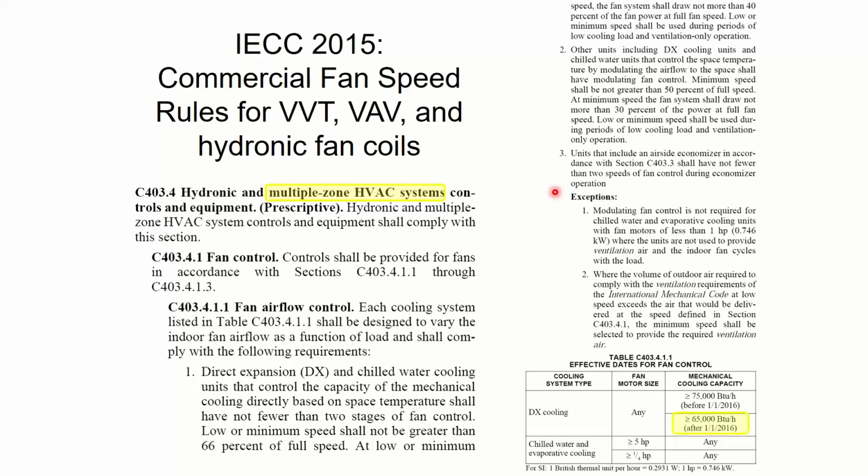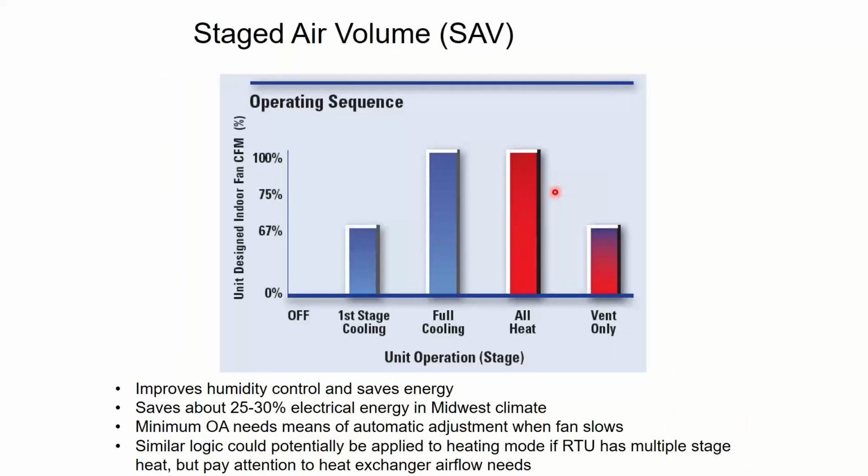We have one more question on the fan speed. The question is, do you need a special thermostat to control the fan speed? Excellent question. If you're just going to do one of these 2-speed fans, you do not need a special thermostat. A regular, everyday, 2-stage heating and cooling thermostat would be able to handle this. I'll show you in a little bit how we wire it to make that happen. But you would not need anything special. Your favorite thermostat, as long as it's a code compliant 2-stage thermostat, would be able to do this.